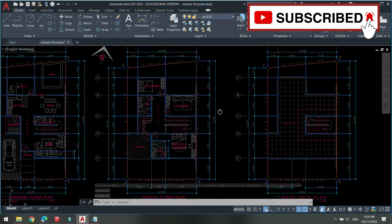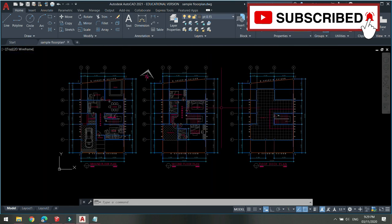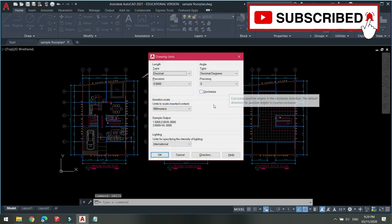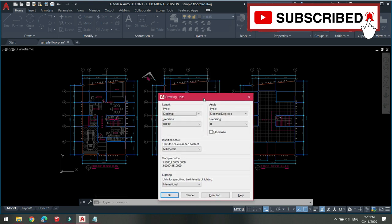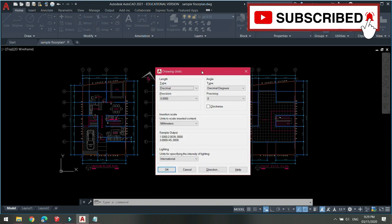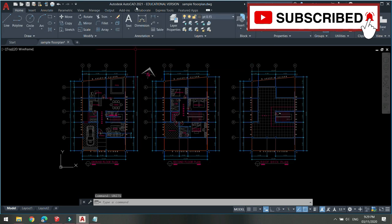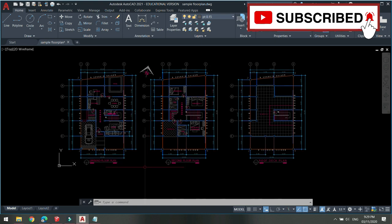So before we actually export or import an AutoCAD file, we should know the version and the units. The units inside is millimeters. I use millimeters, so the most convenient way of exporting is to know the units. So I'm using mm. And the version is AutoCAD 2021. So you should know your version of CAD because importing and exporting may require you to save it to a lower version or vice versa.